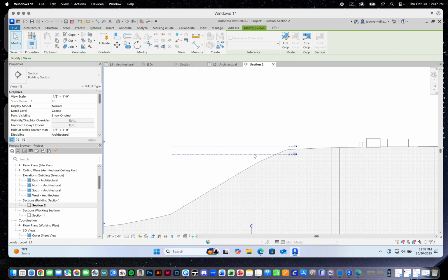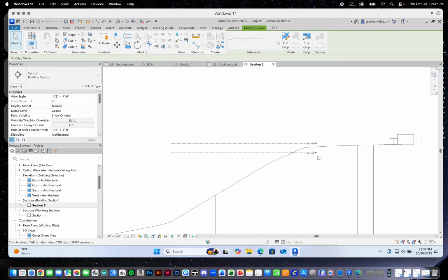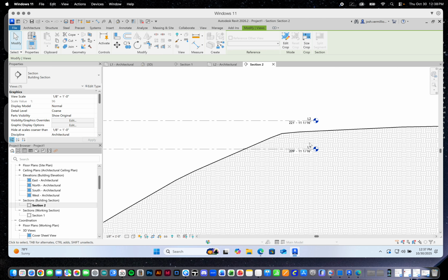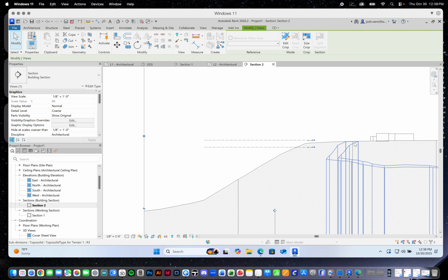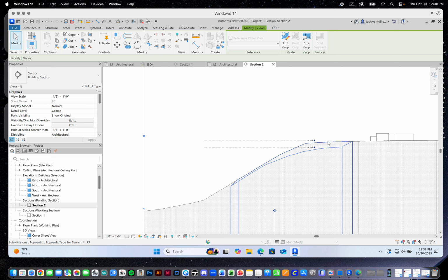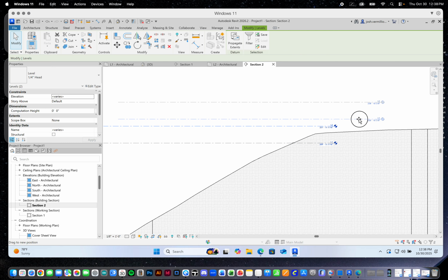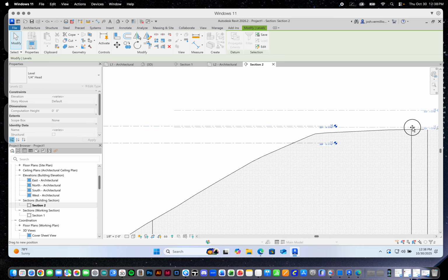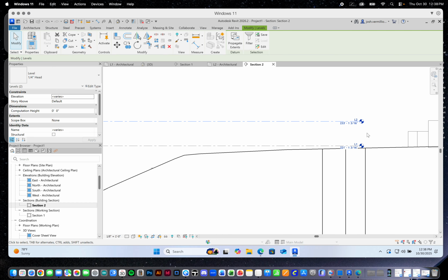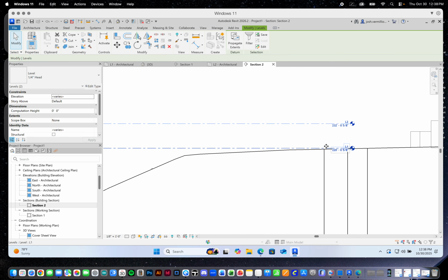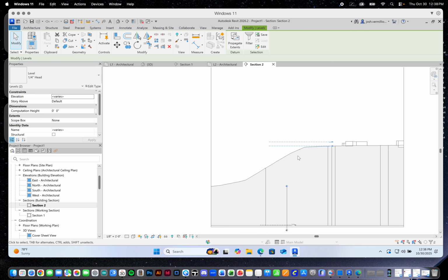All right. So what you can see here is that our section markers, our elevation markers, are levels. Those are called levels, L1 and L2. They're still kind of low, right? Let's say I want to start level 1 of the building just right above grade. I'm going to go ahead and select these again, now that I can see exactly where they would be on our site. And I'm going to move these exactly where I want them to go. Just a little further up here. And maybe right there. Yeah, all right. Beautiful.